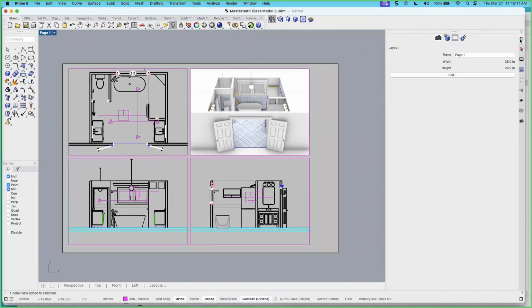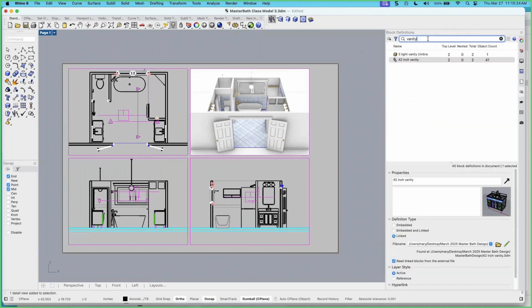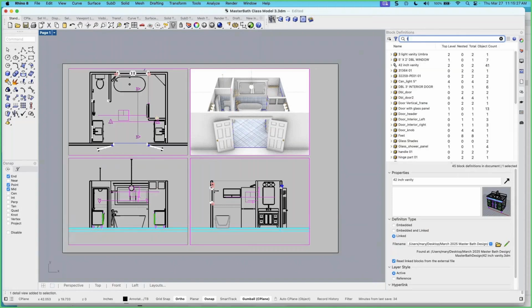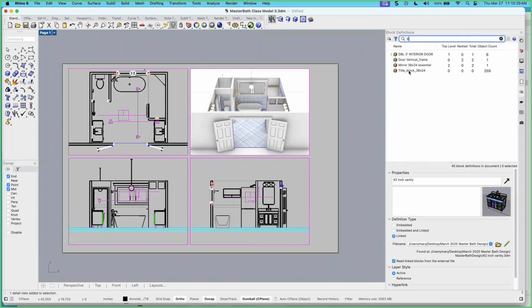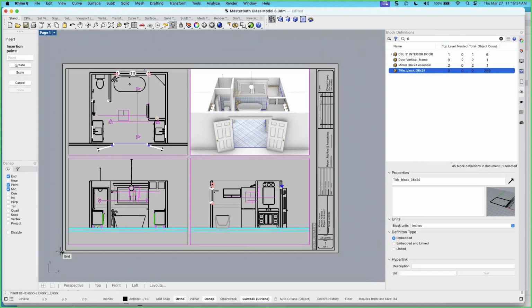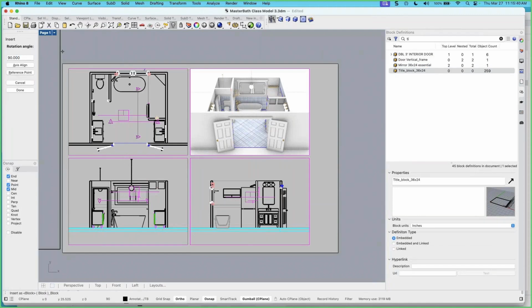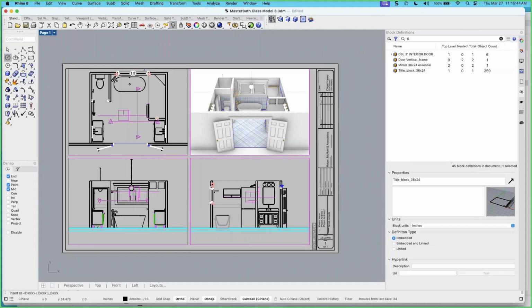And we can add a title block. We have a block in the file set that you downloaded. So this time when I insert the title block, actually I think I have a copy in the file as well, just to make it easy. Title block, insert, we'll bring it in down at this corner. And we'll be a little careful over here with the right mouse button click, since at this point in time it's a little messed up. And now we have our title block.